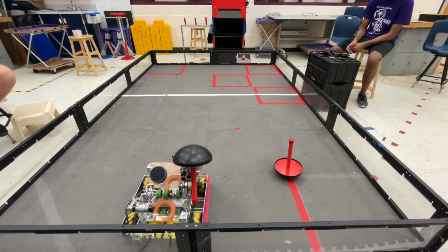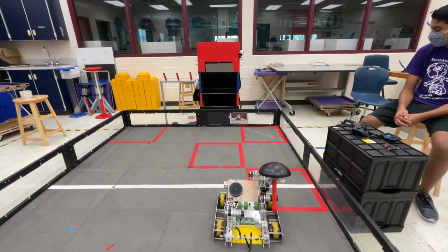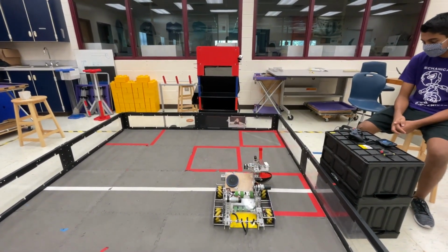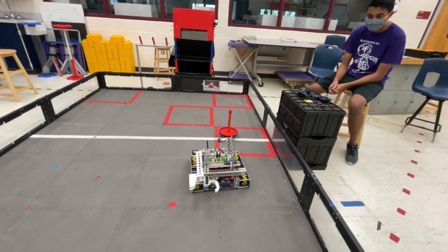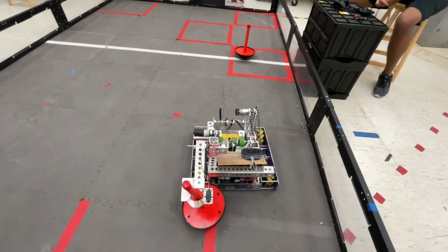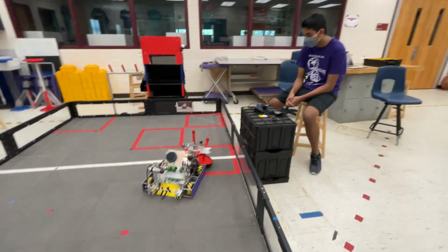Using the strafe direction algorithm, the robot goes forward at a 30-degree angle, then goes right at a 90-degree angle, and shoots the rings into the high goal. Then it places the first wobble goal down, turns using the rotate method, and goes backwards. It then proceeds to pick up the second wobble goal, goes forward, turns around, and delivers the wobble goal while parking with the arm.